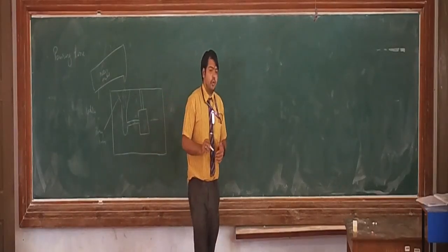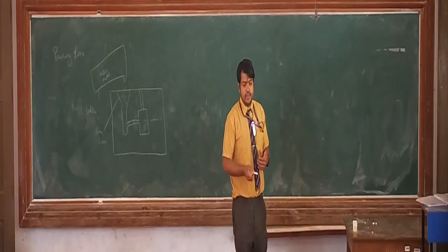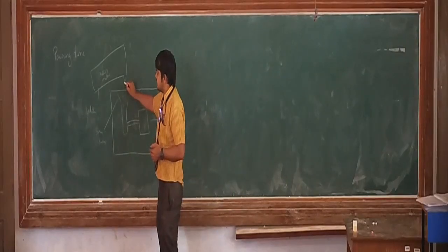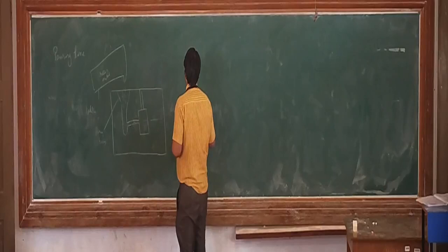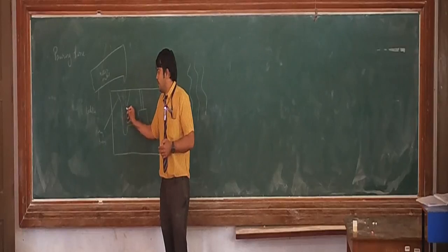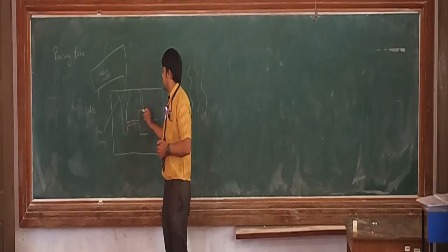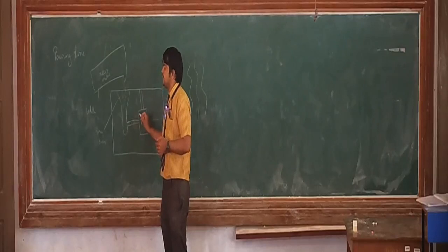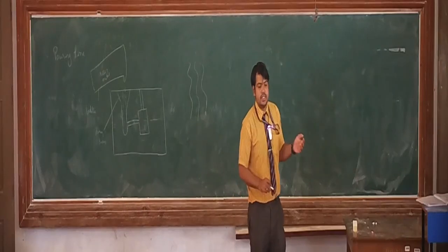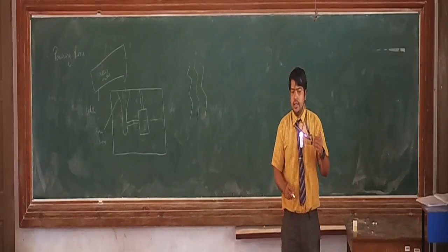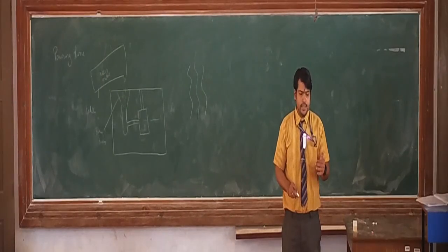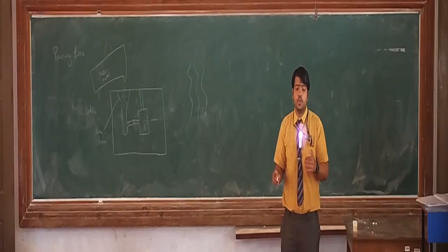If we pour it at a very fast rate, then the flow of the fluid inside this is going to be turbulent like this, and subsequently it is going to damage the walls of the mold. The mold cavity as well as the gating system get damaged because of the turbulent flow. As I explained in the last class, the flow has to be as laminar as possible, otherwise the turbulence has to be reduced. Thus the pouring time should not be too less.